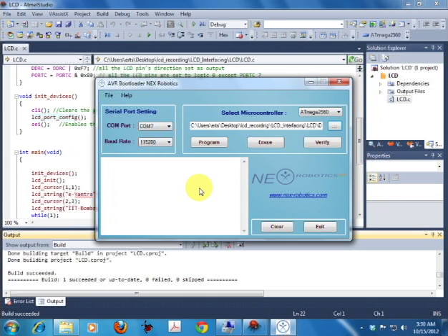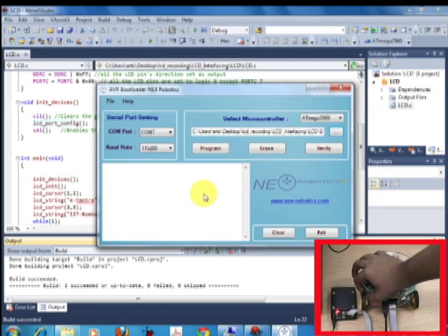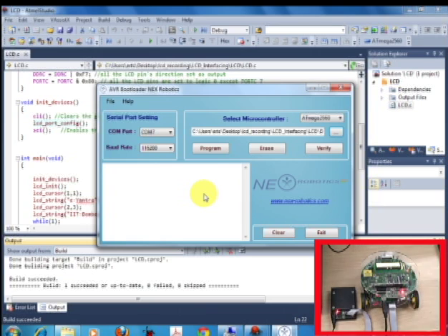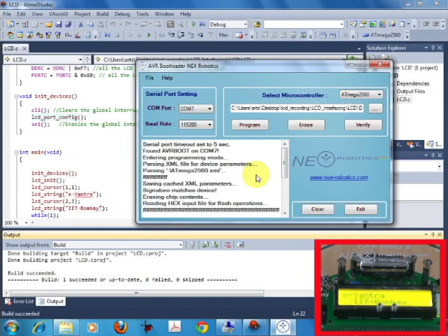and then you can see that Intel hex file. Now switch the robot to bootloader mode by pressing and releasing the reset switch with the boot switch pressed, and then release the boot switch. Then click on the program button and wait for the program to load. Once the code is loaded successfully, switch off and on the robot. So you can clearly see here that we have got the desired output.